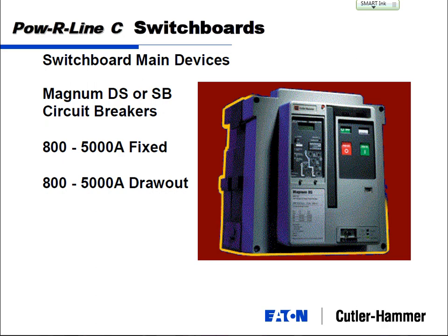The other benefit, and why we use these as main breakers a lot, is you have the ability to have an electrical operation. Opening and closing the circuit breaker here is a physical action of moving this handle up and down. This breaker, it's a physical action with a couple of buttons on here, but there's a spring in here. So I can pump this handle a couple times and charge the spring, and that gives me open, close, open push buttons I can hit to do those. And by that time the spring's uncharged, and that's it.